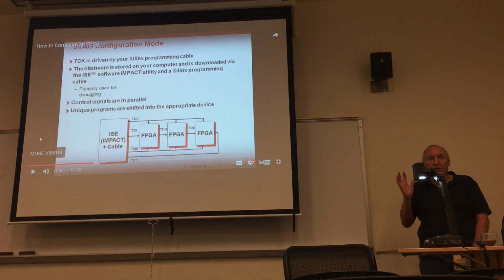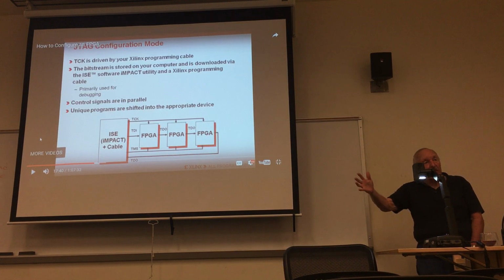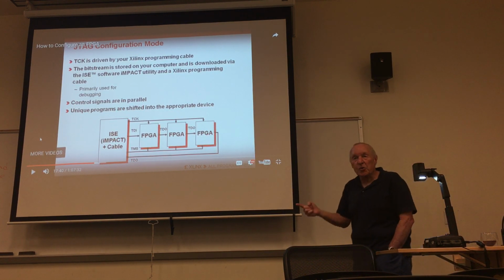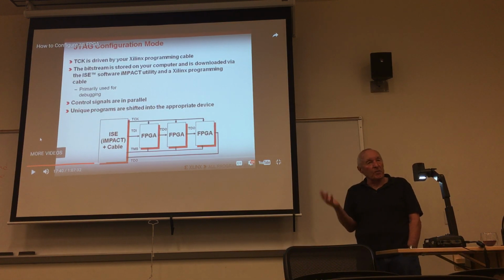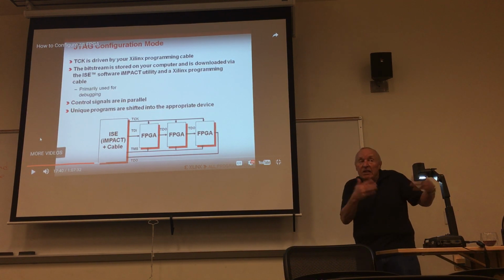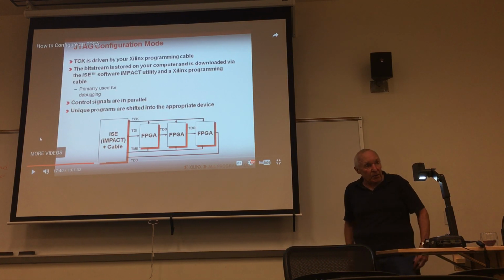mode. In practice though, if I've got a handheld instrument, some embedded application, I don't have that. I'm not using the JTAG interface because I'm not interfaced to a PC. Nevertheless, if something goes wrong and a field service engineer goes out to troubleshoot the printed circuit board, if you provided the JTAG interface, that field service engineer can have a laptop or whatever with test and debug software, and through the JTAG interface, configure the FPGA in some way so that diagnostics can be run.